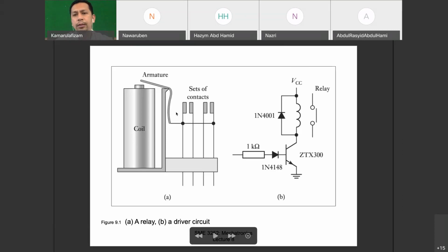So in this case bila ada contact dalam ni, actually EMF akan go back and forth ke circuit, dan biasanya kawan ni akan jahanam dulu, akan rosak dulu, sebab dia tak boleh tahan the EMP, the electromagnetic pulse yang di-create oleh contact point. So untuk selamatkan kawan ni, you have to have a diode kat sini yang akan sekat perambatan back EMF tu.